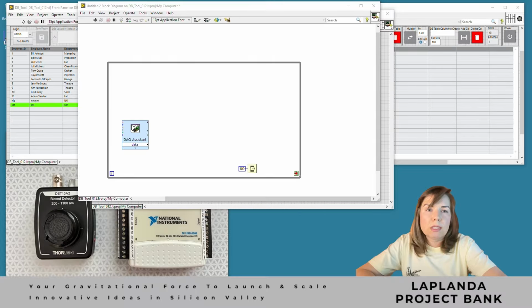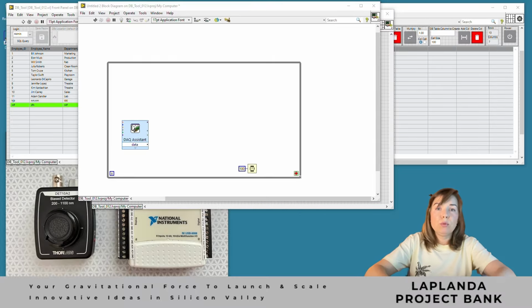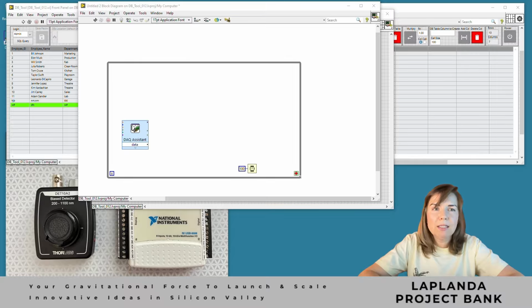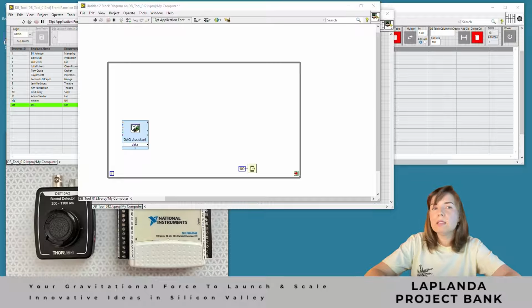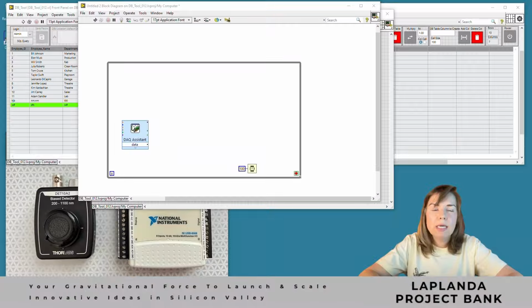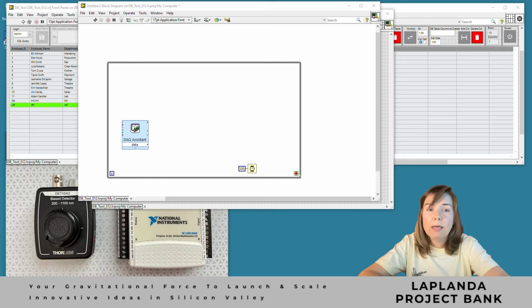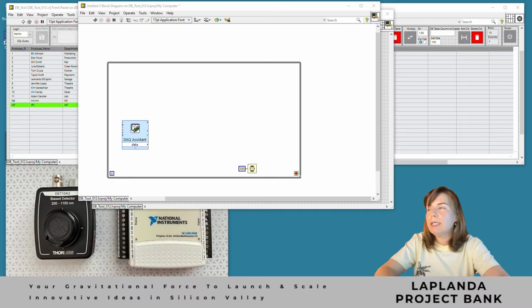And I should say here that Windows limits the speed of our operations. I won't go deep into the details, let's just accept that the average delay will be about 10 milliseconds. This is because our command passes through Windows services that are routed to the processor along the required path. So if we want to work in true real time, this system will not be suitable for us, and we would need to use other methods that exist in our program. For example, real-time applications and various systems like PXI or Rio.